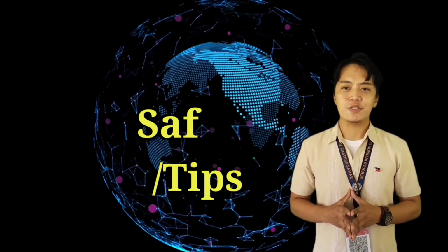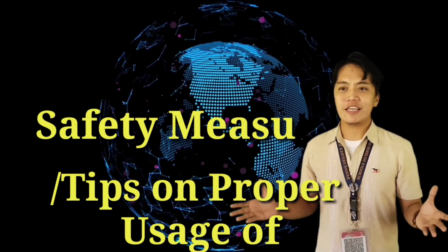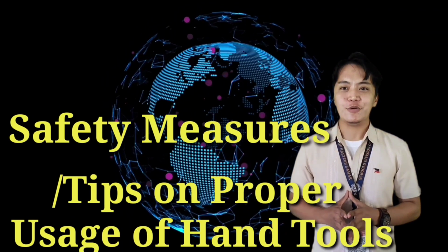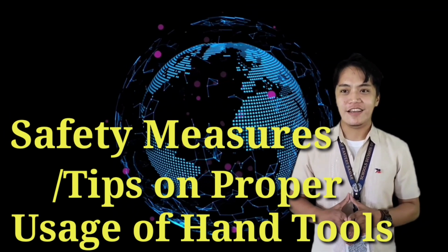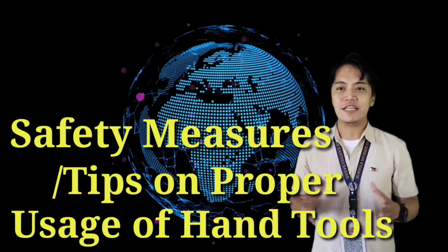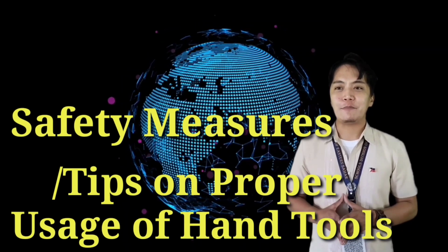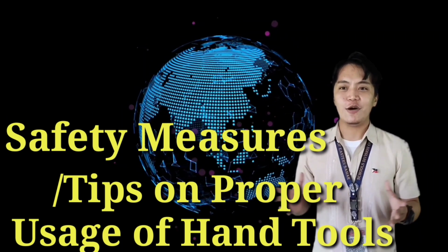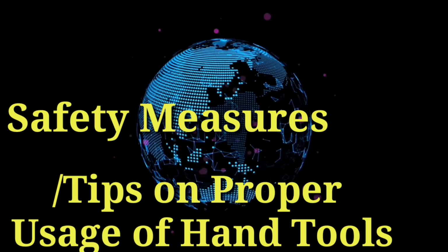Remember that several tools are magnetic. When working around electronic devices, take care that the tools you're using haven't been magnetized. Magnetic fields may be harmful to data stored on magnetic media. Check your tool by pointing the tool to a screw. If the screw is drawn to the tool, don't use the tool.